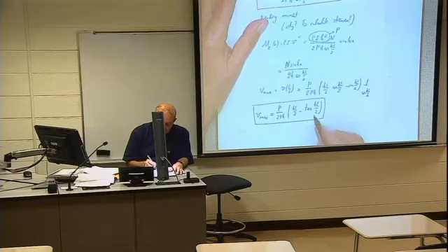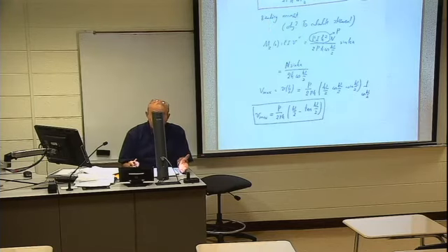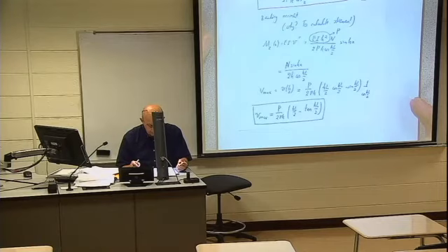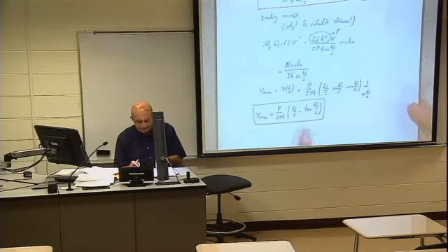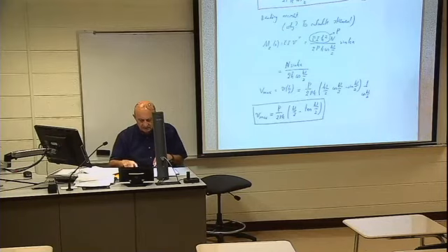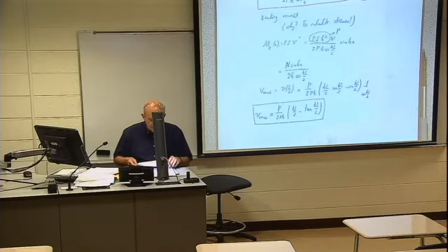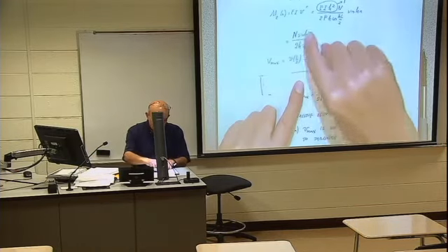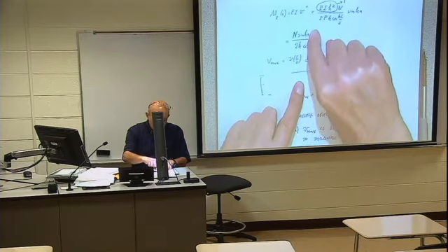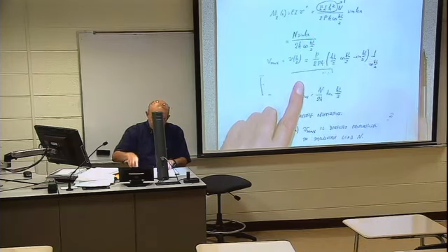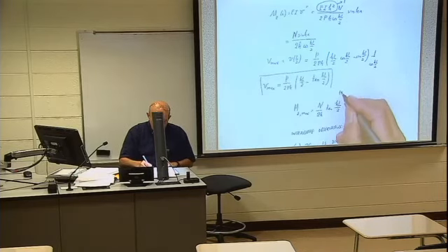Sine over cosine is tangent. You see, we also need trigonometry, otherwise, without it, we cannot get anywhere. So that is V maximum, the maximum displacement. M maximum: sine kL over 2 divided by cosine kL over 2 will be tangent kL over 2. So 1918.